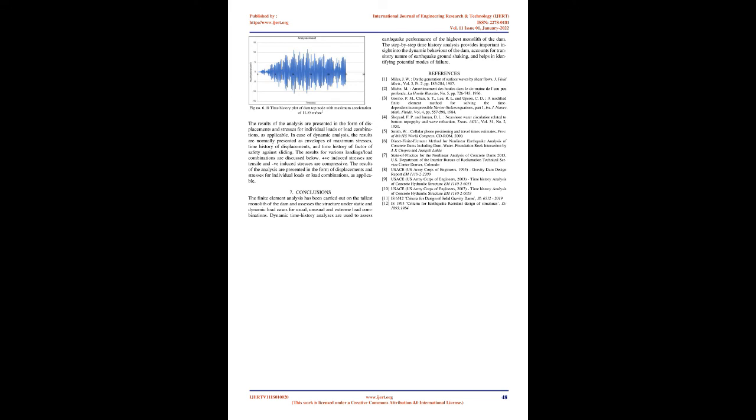6.1 Time history of displacement. To assess the dynamic response of the dam, time histories of displacement and acceleration response of the structure are obtained for simultaneous application of horizontal and vertical ground motions corresponding to the DBE and the MCE.